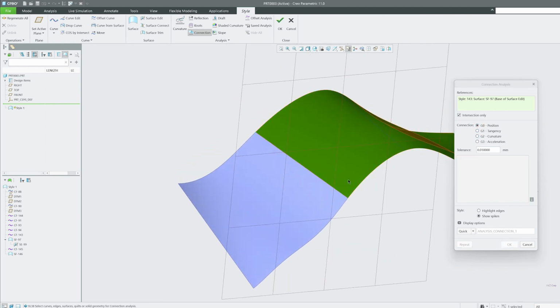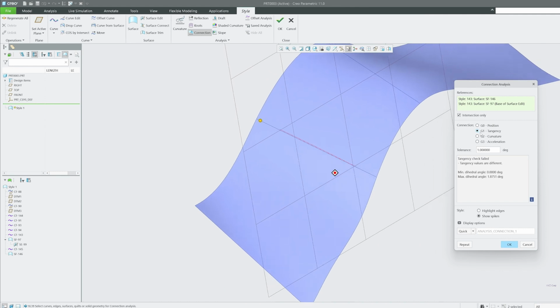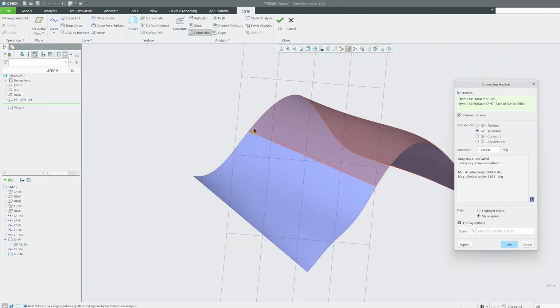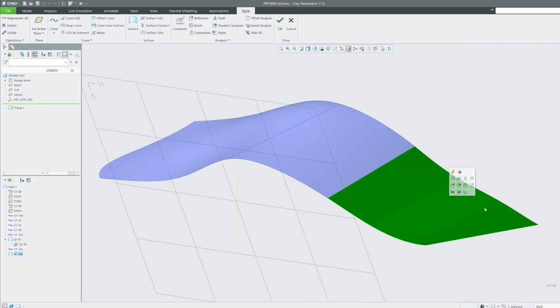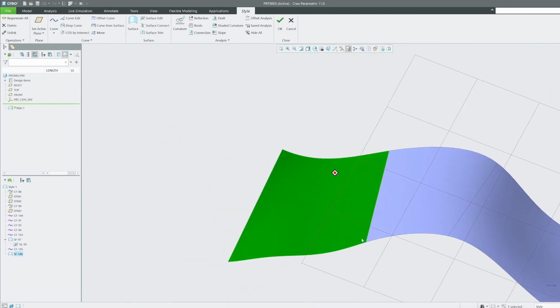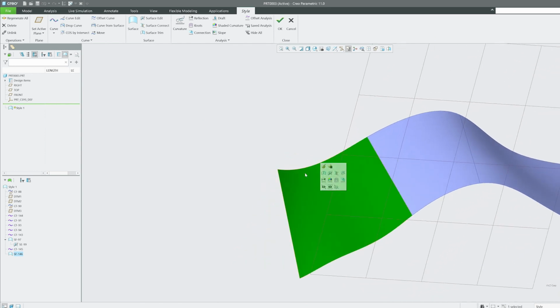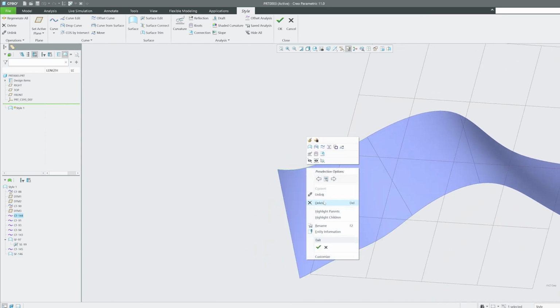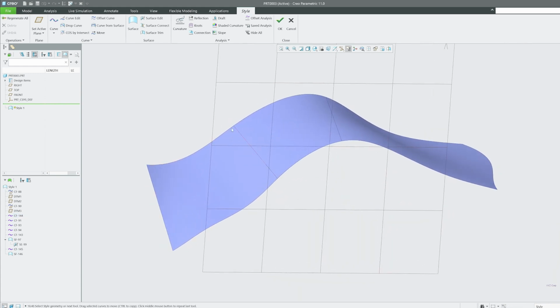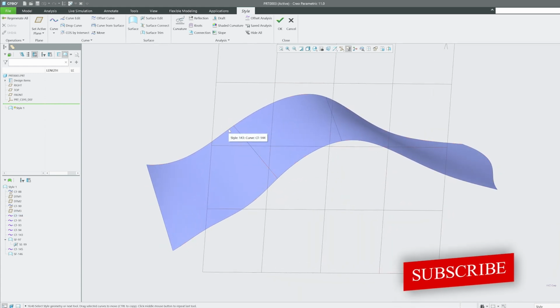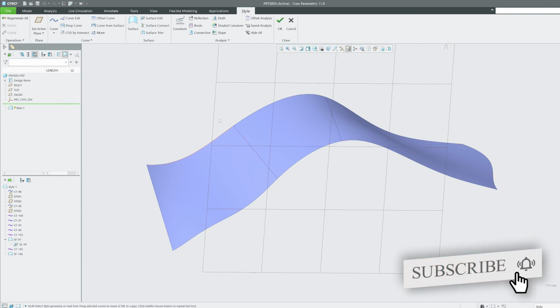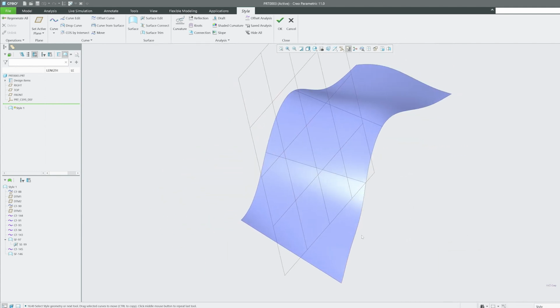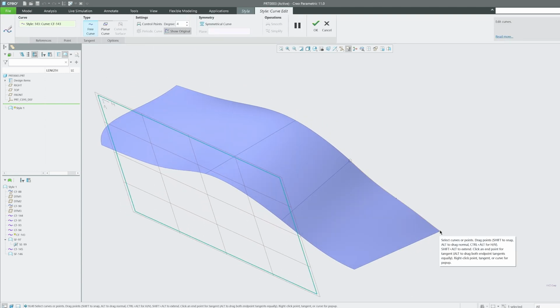and let's select the intersection, and here we can see that despite now having created a G2 type connection at both these curves, we are still seeing it fail. The reason why this is happening is that on both sides the curves are different. So if we want to produce something that can easily pass, then we probably also need to change my curve. The reason why it still fails in case of surfacing, despite having G2 curvature at both ends, is that both these curves are entirely different, and the way they are placed.